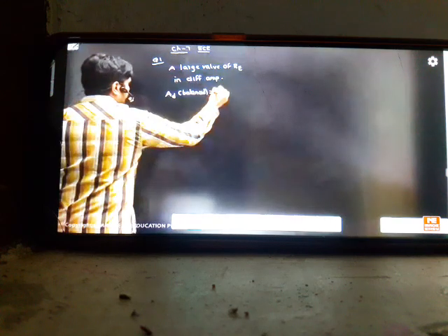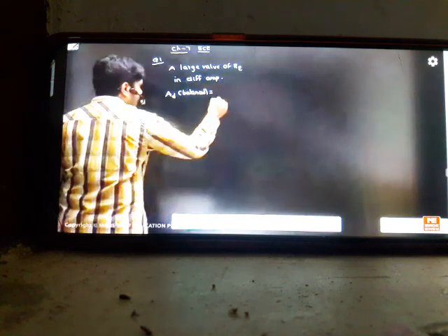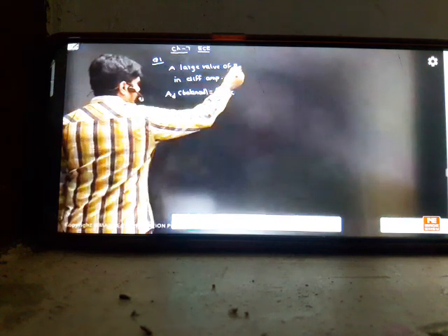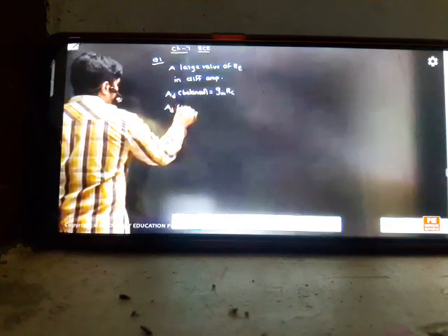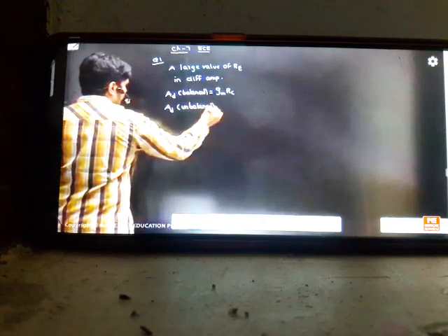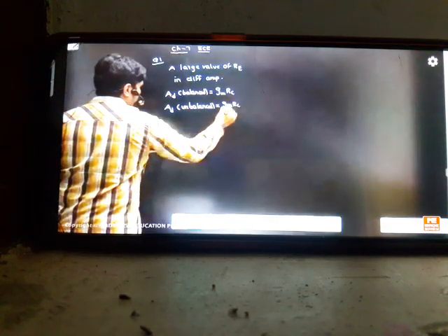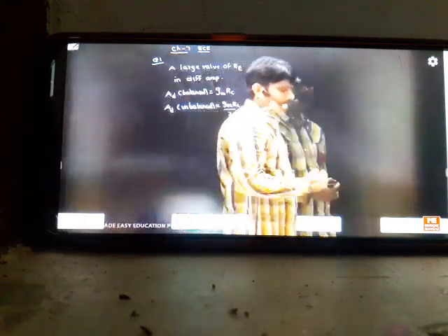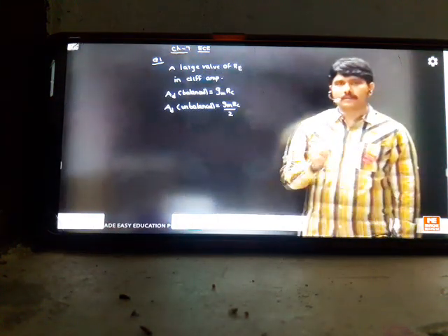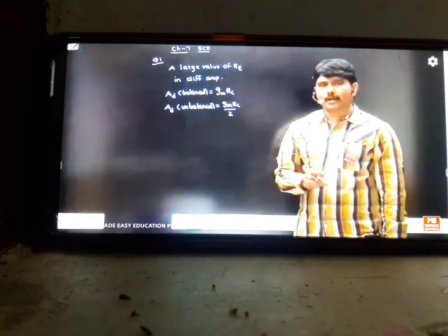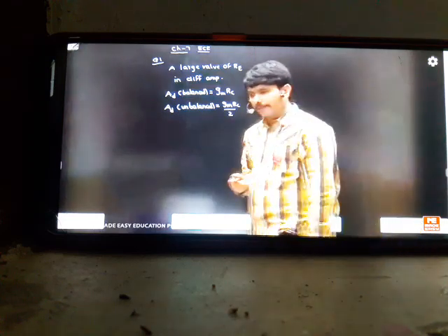It is gm into RC. It is the transistor gain. In this formula, I am not seeing any RE. And AD unbalanced, you can easily recollect this formula too. It is gm into RC by 2. So these are called balanced gains and unbalanced gains. One thing is very clear: balanced or unbalanced, differential gains never depend on capital RE. RE will get shorted in your AC analysis. If you have any doubt, you can go back and see the concept once.